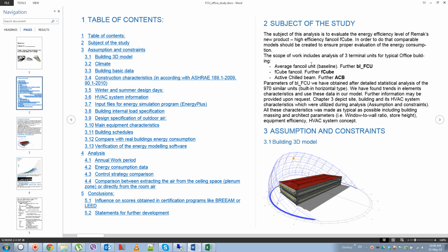It means how many watts of cooling it provides per 1 cubic meter per second of primary airflow. And we picked some average value for that, but it is only a question of price, so it is not efficient, because an active chilled beam is a passive component and does not consume any energy and uses energy from the air which was energized by the air handling fan.